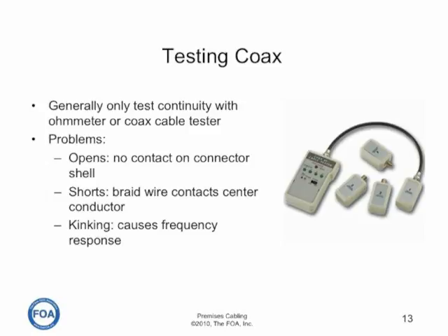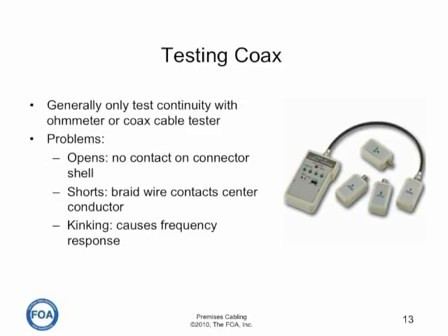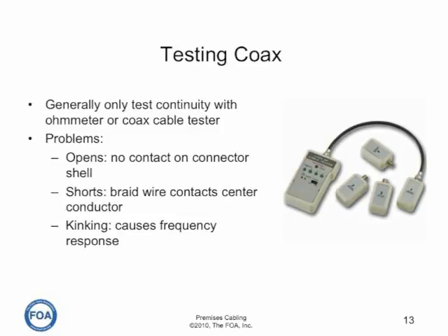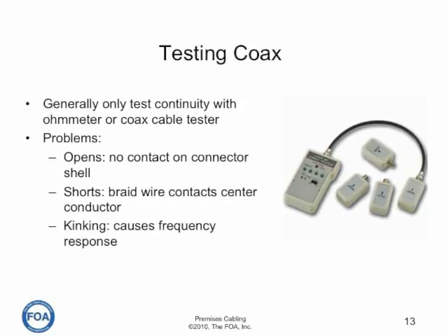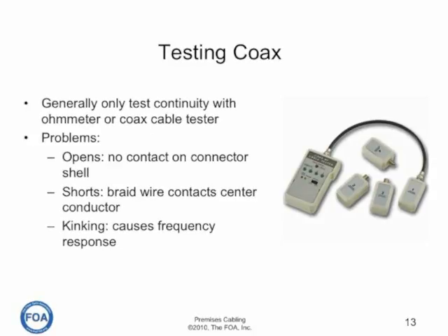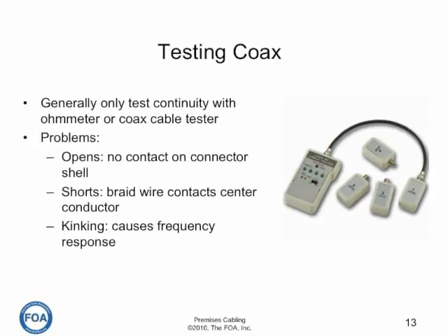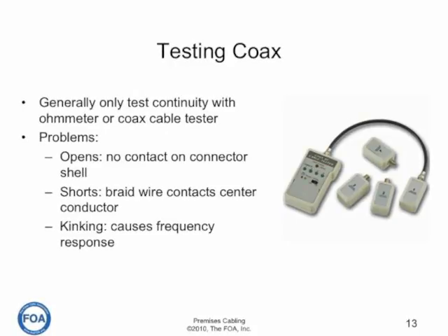shorts, where wire braids contact the center conductor, or kinking. We didn't talk much about installing coax cable because it's just like installing any other cable. But because of the particular construction of coax cable, it's very sensitive to kinking. If you kink the cable, you may affect its high frequency performance. So like every other kind of cable, be very careful when installing it not to put kinks in the cable.